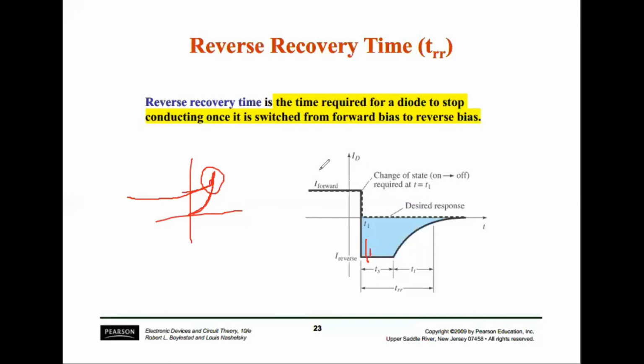Okay, so this is that point where it will stop conducting and will be changing its direction. Just like if a car is moving and you want to reverse the car. If it is moving in the forward direction, you want to reverse it. For some time you will have to apply the brake and it will stop. The time for which it is stopped is called the reverse recovery time. Okay, I think now it's understandable.